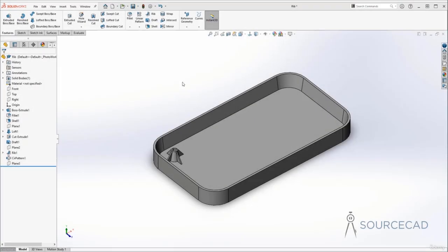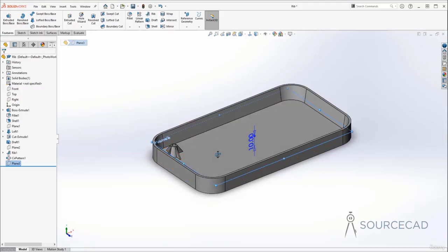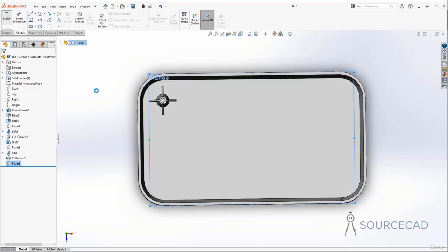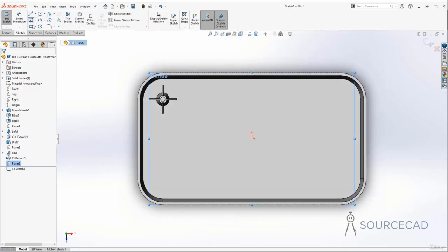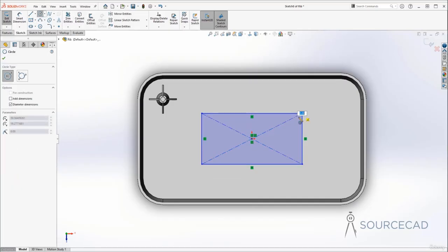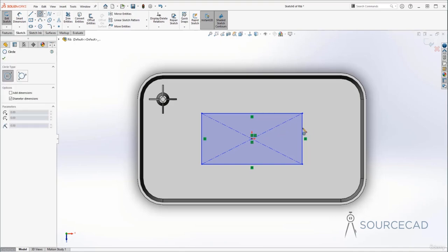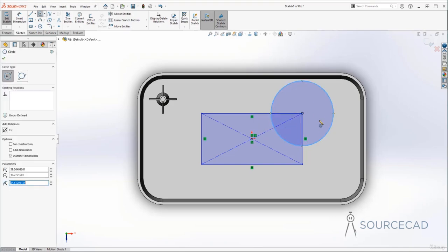Now finally, let's talk about creating this rib feature with contours. So far we have used sketches. Now in this case, we won't use a sketch, and instead we are going to use contours, closed contours. So I'll select plane 3, which is the plane which we selected previously for creating the linear sketches, and I'm just going to create a simple drawing here. So I'll go to sketch, and maybe I'll just create a rectangle here and then a circle right here. So well, let's just do that again. So from this endpoint, I'm going to just create it like this.